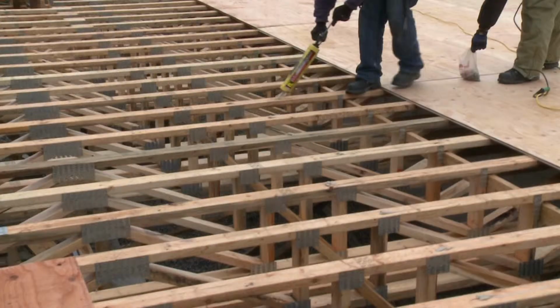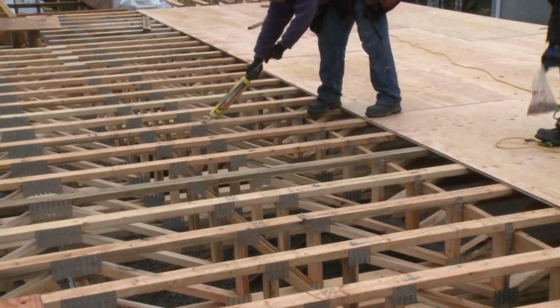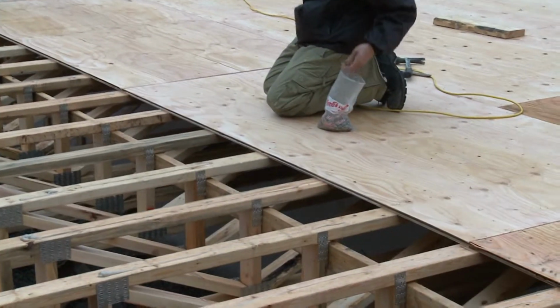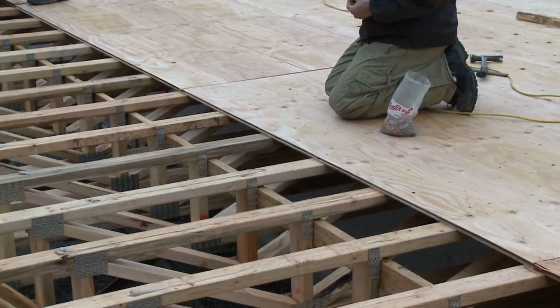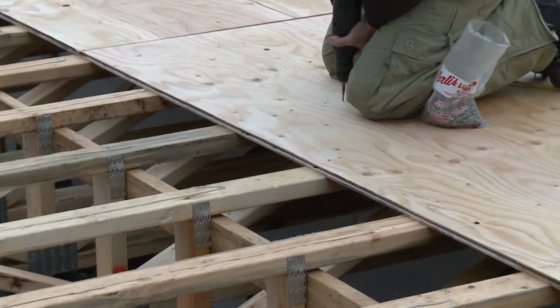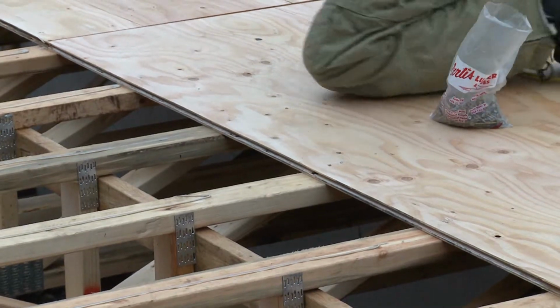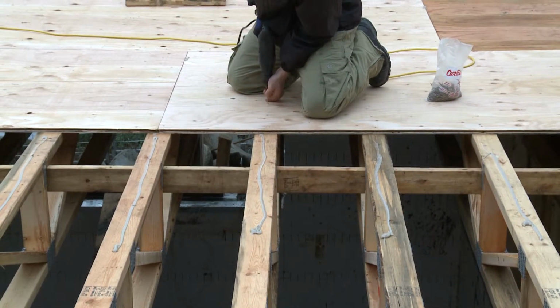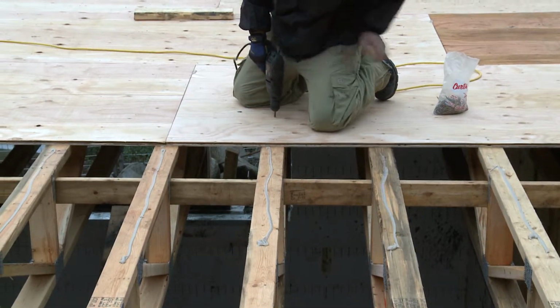On top of that, the roofing materials are quite heavy as well. And for wind load, we take the kind of wind towers in the roof structure. So we need very stable beams and columns. I picked engineered wood, which gives very strong elements and a lot of stability. It's very precise. There are no cracks or any shrinkage, which gives very stable conditions.